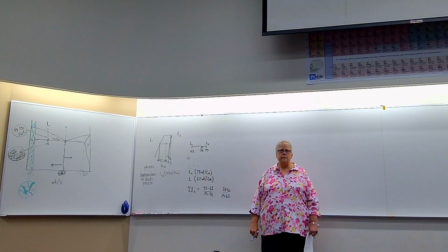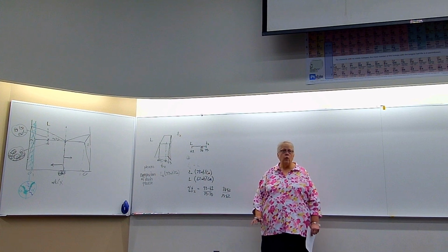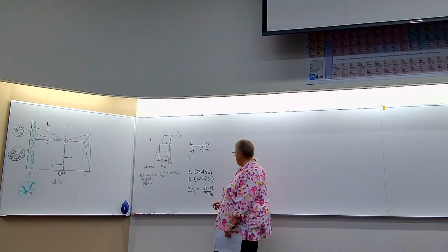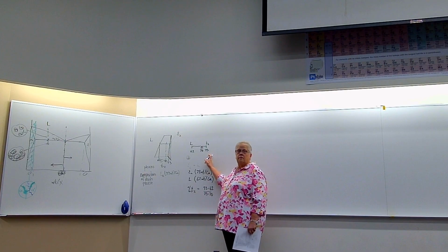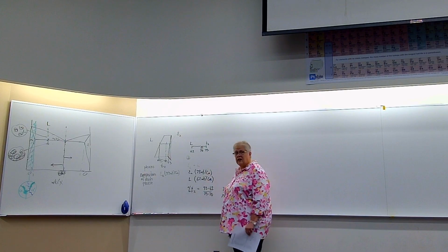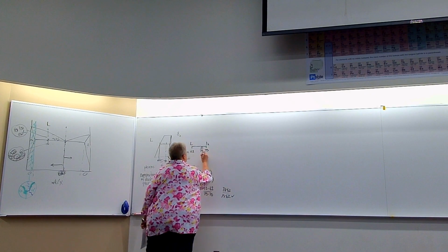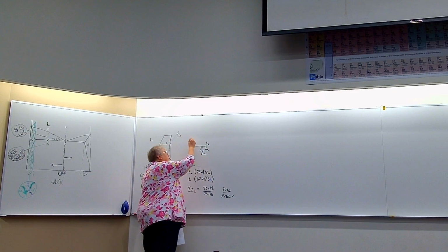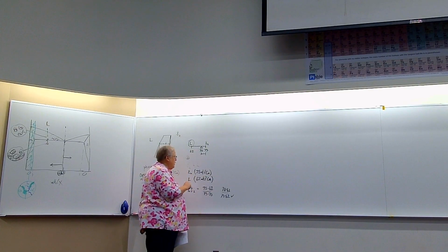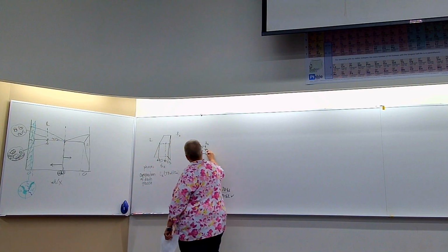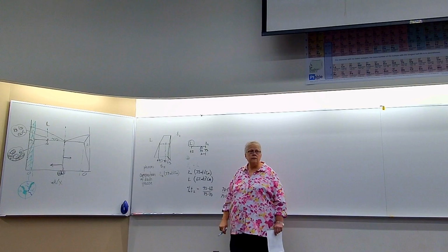Anybody have another alternative? Okay, well, first of all, the denominator should be the whole length. Okay, so this is correct. Now, 70 minus 73 or 73 minus 70, this side length tells me about the percentage of this over here. Always on the opposite side. All right? So 73 minus 70 over 73 minus 62, that would be the percent liquid.